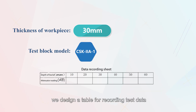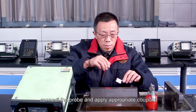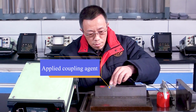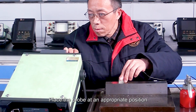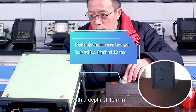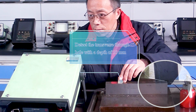First, we design a table for recording test data. And next, connect the probe and apply appropriate couplant on the detection surface of the test block. Place the probe at an appropriate position on the detection surface and detect the transverse through hole with a depth of 10 mm on the test block.